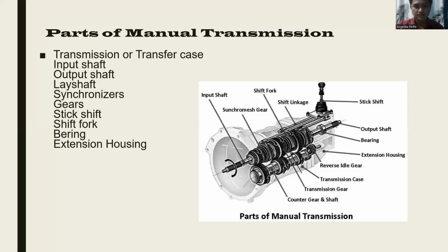Counter shaft. This is also known as the lay shaft. It rotates in the opposite direction to the input shaft. It spins whenever the engine is running and the clutch is engaged, and it drives the gear selected by the driver on the main shaft.